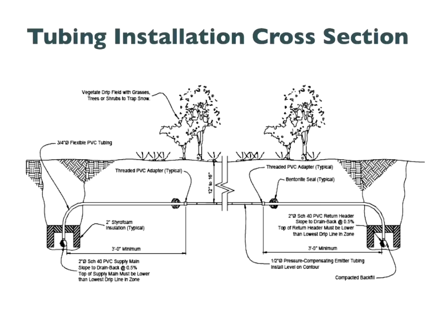Okay. And here is Scott Wallace's technique, where he actually includes a bentonite seal to prevent water from flowing back into the tank. Of course, if this distance is long enough, I don't know anybody other than Scott Wallace that does that. But I'm not opposed to it. Okay, and this is the drip line here, and that is the bentonite seal there.